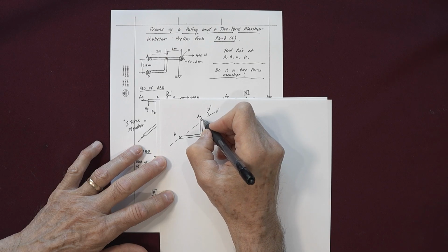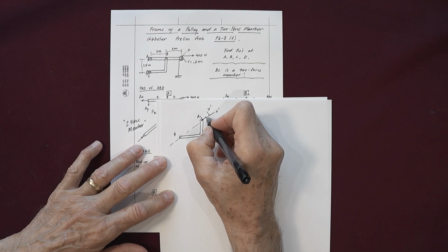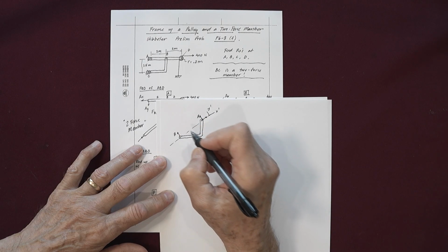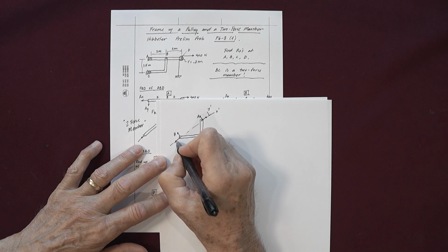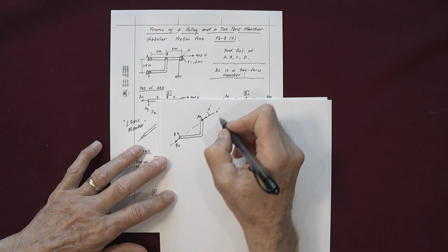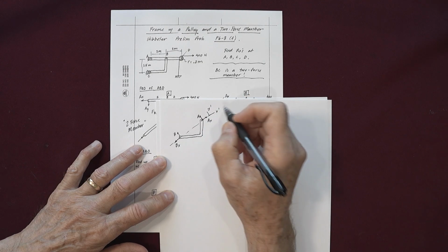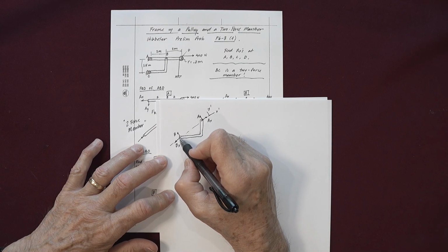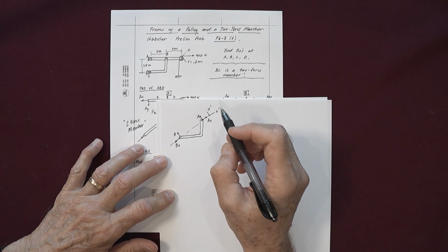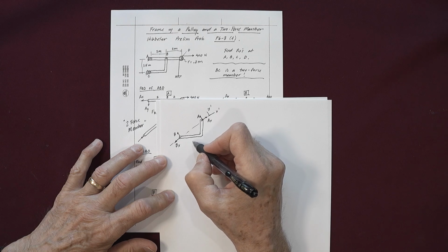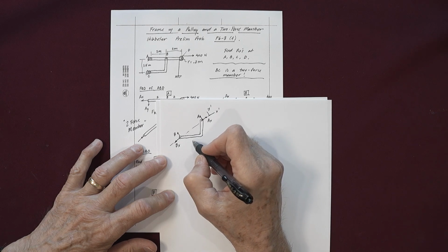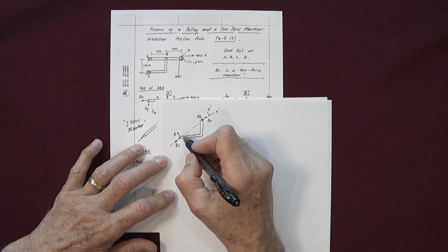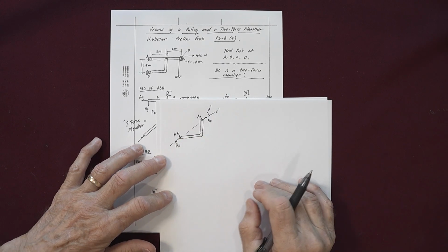If I put an AY prime and an AX prime here, and a BY prime and a BX prime here, where the X prime axis is along the straight line drawn between these two pins, and there's no other force acting on this member, no couple, no force, no weight, then the only forces acting on this member are at the two ends, at two points.